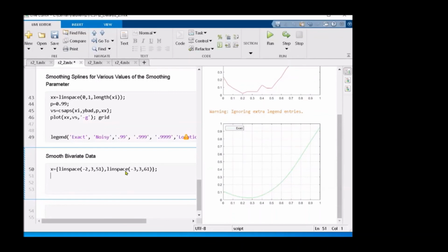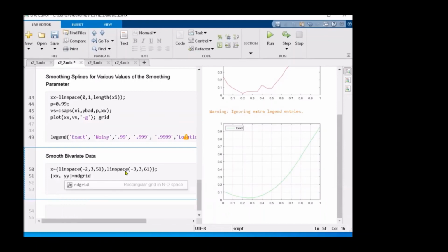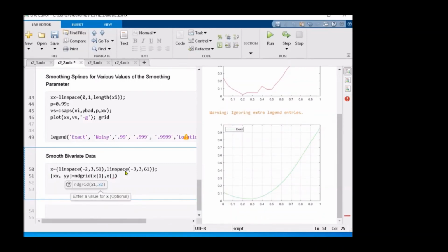Okay, now we can make the gridding. By the way, we can use different functions for mesh. We can use meshgrid and we can use ndgrid. Somebody knows the difference between ndgrid and meshgrid? Please tell, while I'm writing. Maybe you can decide the size of the mesh grid. Right, yeah, you are right. Meshgrid is convenient only for 2 variables, just for plotting a 3D plot. But ndgrid can make meshing for many arguments. It could be 4, 5, 6, a high-dimensional array or matrix.